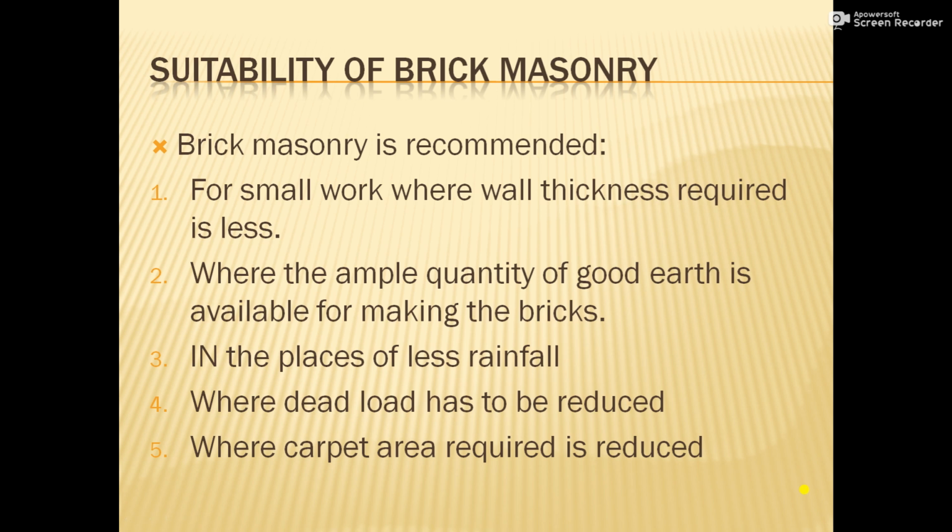Now the next point of the study is the suitability of brick masonry: where we can use brick masonry and where we can use stone masonry. First we will see where brick masonry is recommended: for small works where the wall thickness required is less. Whenever the work is small and the walls required are thin, at that point we use brick masonry.